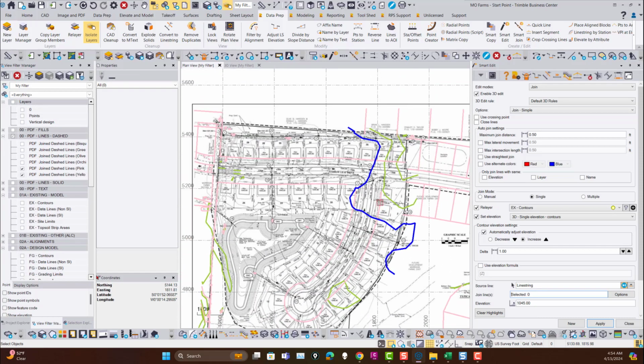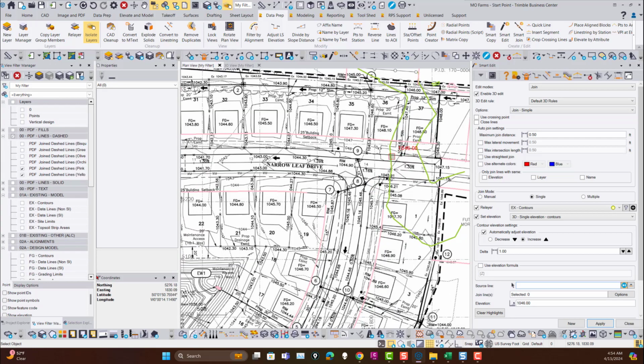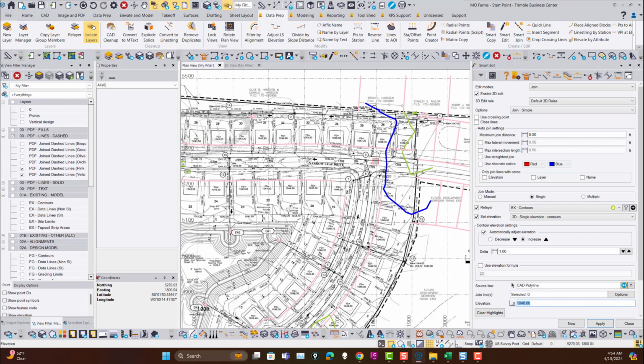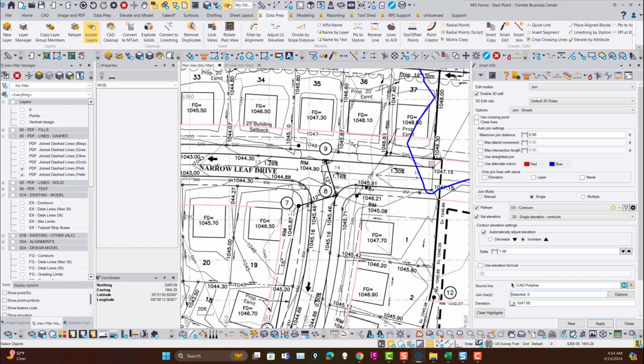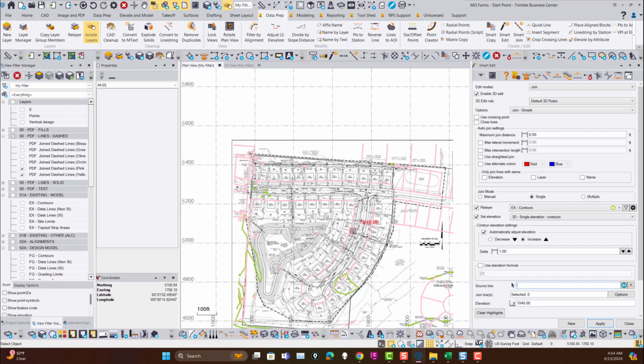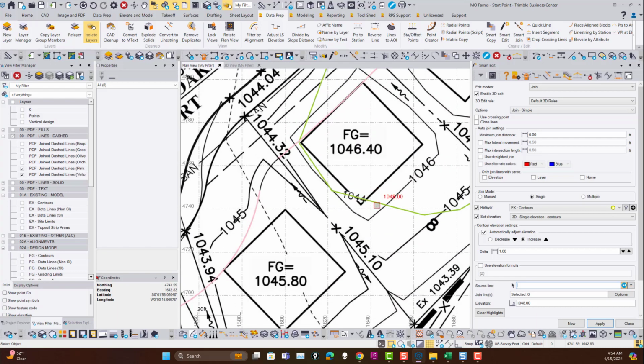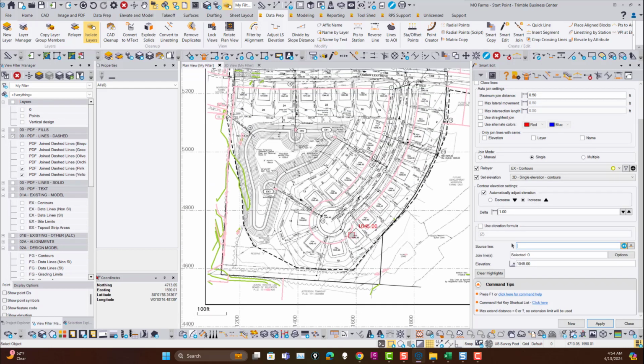That's that one to that one. And enter. 1046. And enter. 1047. And enter. This one down here is a 1044 contour. So I can either use that Shift X again, or if I want to, I can just use the Z key and keep moving the Z key down until I get this down to here. So Z is decrease, C is increase. So you can change this, and the update on the cursor happens when you move the cursor. So I'm on 1044 and I want N, enter, and that's done all of the contours over here.